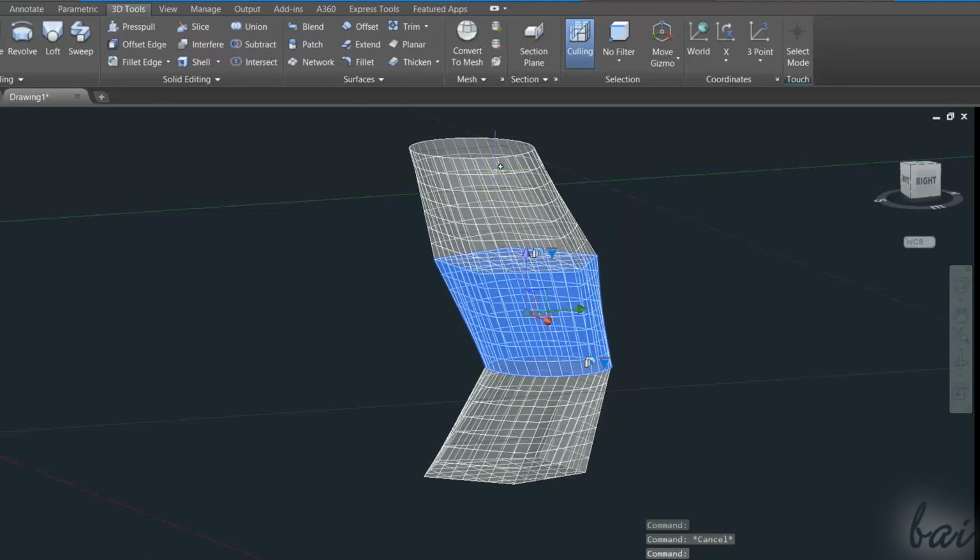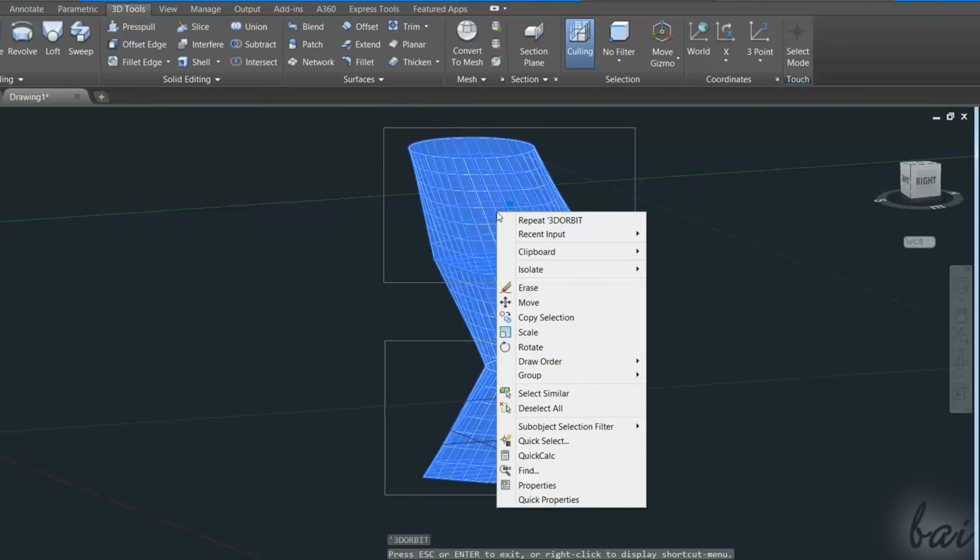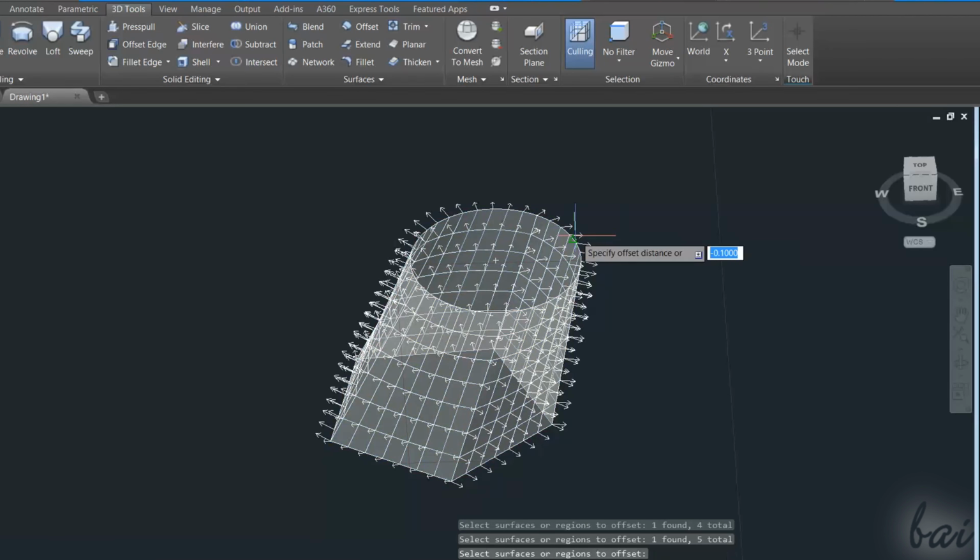In case you use tools that create new surfaces, remember to group all the surfaces to manage all of them in the same way. Use the Offset tool to create a second surface with a constant distance or offset from the original surface. Select the interested surfaces, apply with the Enter key, and then check the small arrows that indicate where the new surface will be placed.